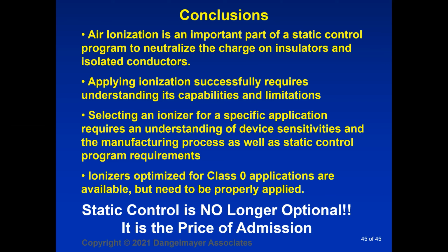Selecting an ionizer for a specific application requires an understanding of device sensitivities. You need to make sure that you choose an ionizer with a balance level that's appropriate for your sensitive devices. And you have to understand the manufacturing process.